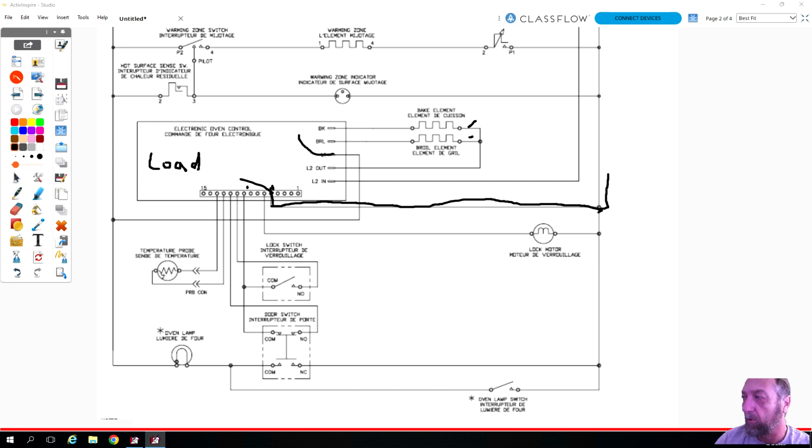So if we look at this board here, you've got to look at this connector, and if you look right here by my finger, you'll see a number 1 just below that black relay right there. And then if I go across, let me see if I can get it on the screen. That's plug number, I can't see the number backwards, P5. But that's pin number 1. So if I count over, pin 1, pin 2, pin 3, pin 4, pin 5, pin 5 is that bent pin. So that's going to be my neutral.